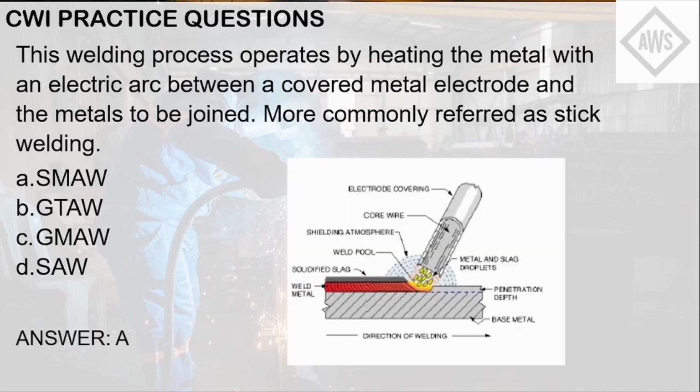So the answer here is that stick welding is known as SMAW. As you can see, the flux coating of the electrode produces a shielding gas that protects the weld pool from harmful atmospheric gases that will embrittle the weld.